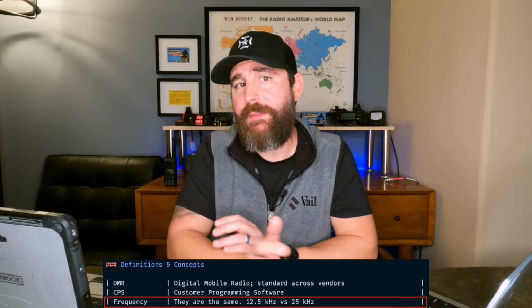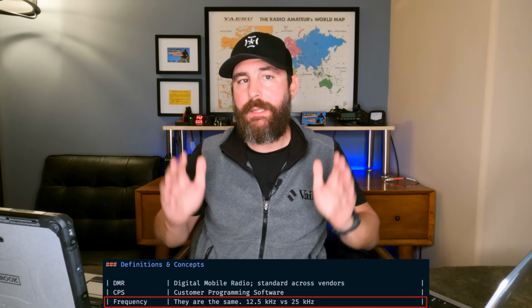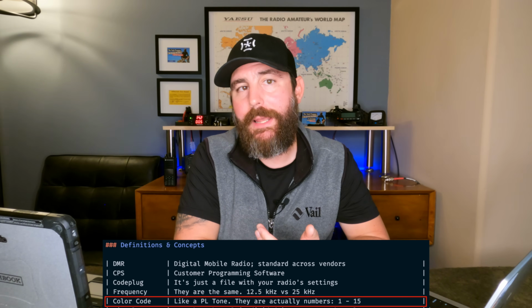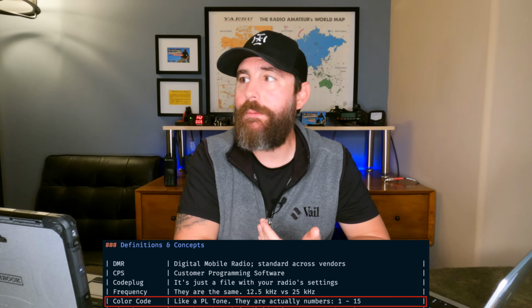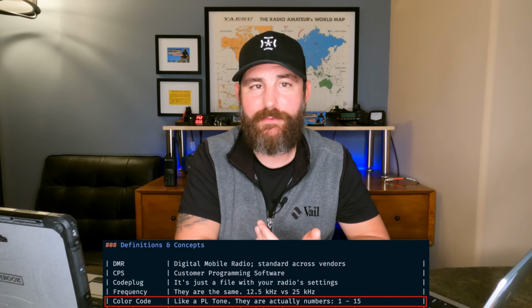Frequency is the same in the analog and digital world. The only difference is that in the analog world, it's 25 kilohertz wide in terms of bandwidth. And for DMR, it's exactly half of that. It's 12.5 kilohertz. Color code. I like to think of color code as a PL tone. In fact, it really has no colors whatsoever.